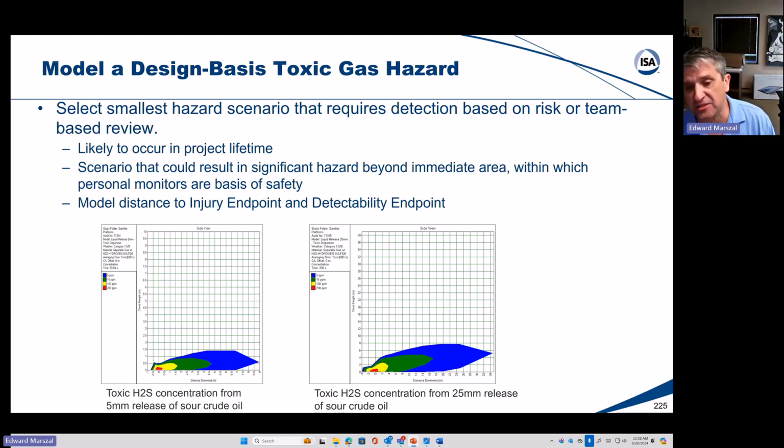At Connexus, when we issue a report, we generally give 1 meter. We basically say that our results are going to be accurate, plus or minus 1 meter, X, Y, Z, any direction. 5 meters is a lot.